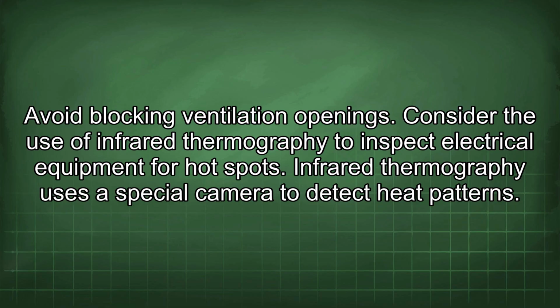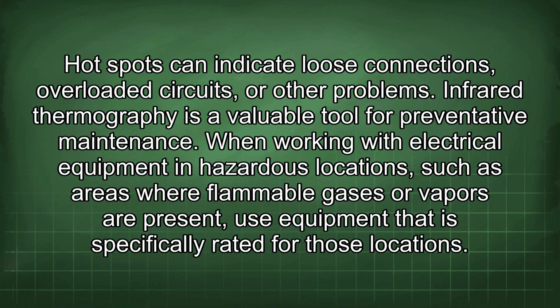Avoid blocking ventilation openings. Consider the use of infrared thermography to inspect electrical equipment for hot spots. Infrared thermography uses a special camera to detect heat patterns. Hot spots can indicate loose connections, overloaded circuits, or other problems. Infrared thermography is a valuable tool for preventative maintenance.